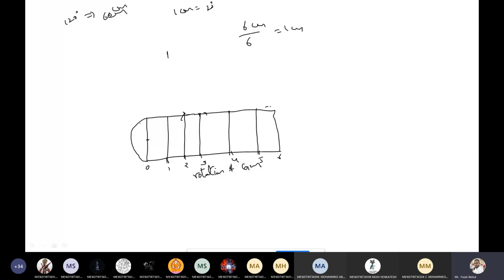Okay, now after drawing the semicircle, divide the semicircle into 6 equal parts, because at the beginning we divided the horizontal box into 6 equal parts. So what is the procedure to divide into 6 equal parts here? Because this is the angular manner. So how many degrees does a semicircle have? Semicircle here total 180 degrees.